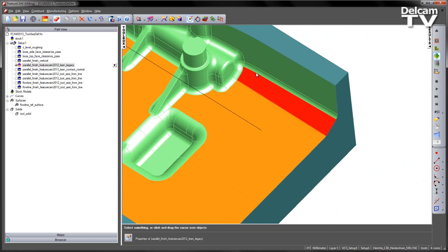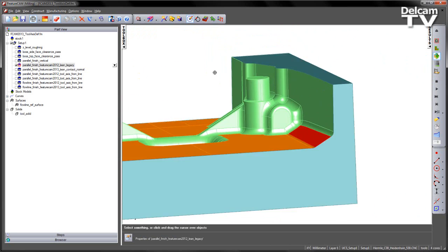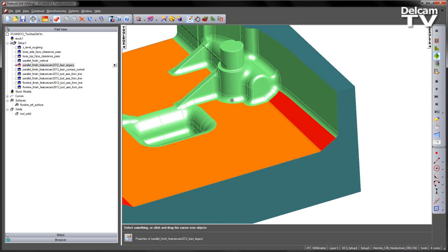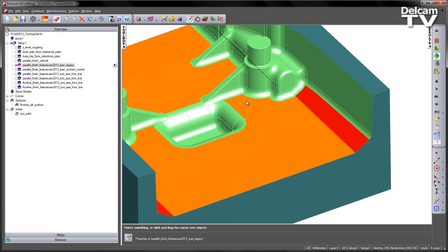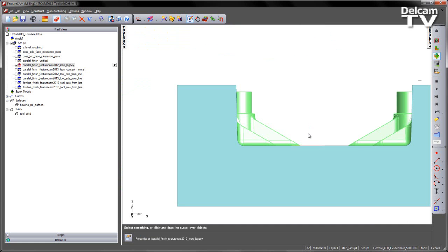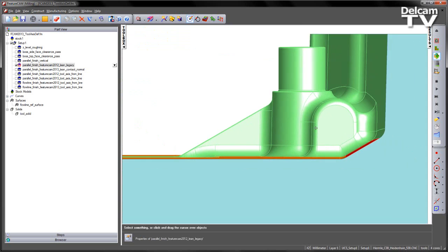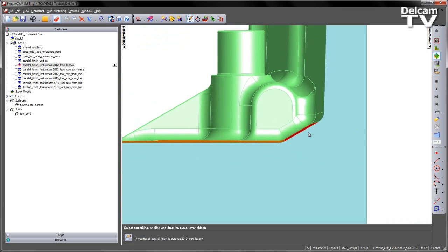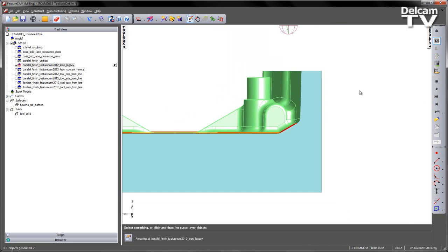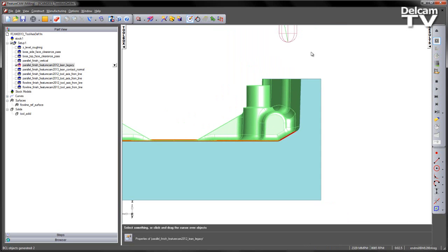Here you can see I'm going to orientate the tool over using a lead-lean orientation. So the idea here, if I view from the back of the part, is I want to orientate normal to this surface. In previous versions of FeatureCAM, for example 2012, if I go ahead and orientate the toolpath, you can see the tool still appears to be vertical.